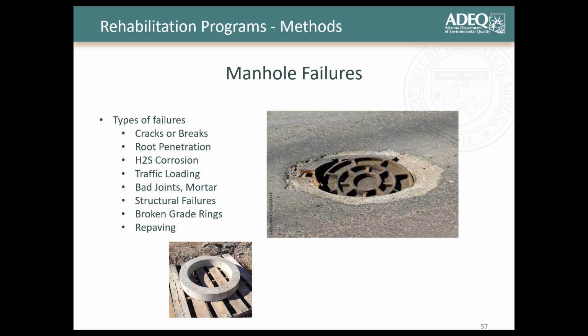If you guys don't know what a grade ring is, I've included one in that bottom left, right? These concrete grade rings are kind of little tools that are used. They make them, I forgot what they are, kind of like a reinforced plastic now, or composite cover grade ring now. These things elevate your manhole structure from the barrel up to the actual manhole ring and cover. So these grade rings elevate you to the right surface area. So that's what that is.